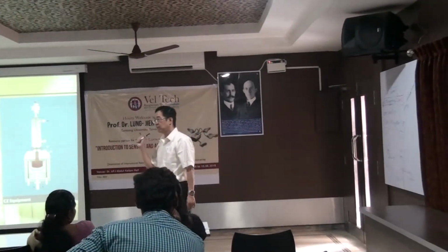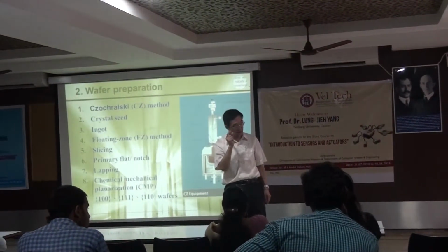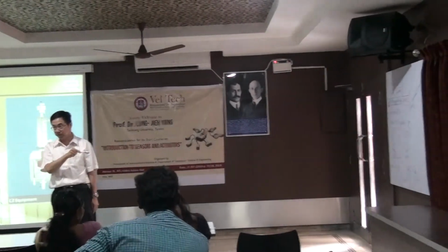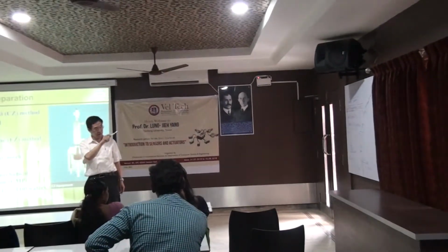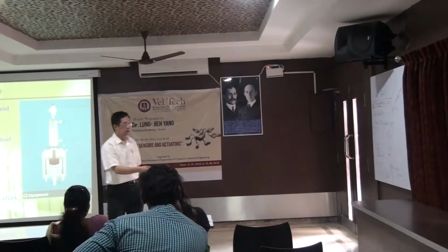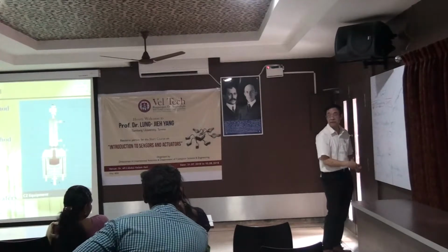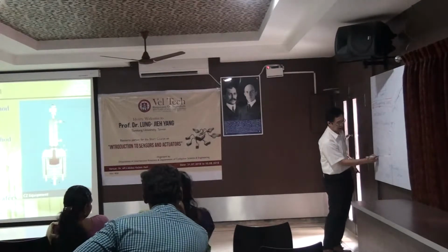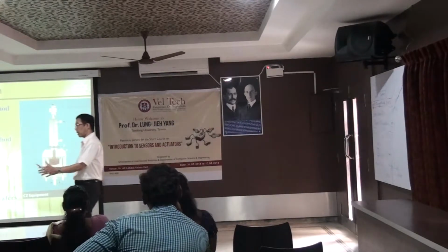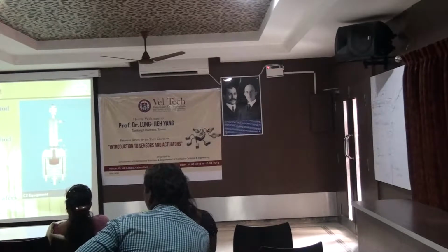More area can make more devices for you to sell. So we want to earn more money, and only leave a little bit of notch. The direction guidance is quite enough for us. So this notch is exactly the same as the primary flat. It's an alignment mark, and we must follow it.